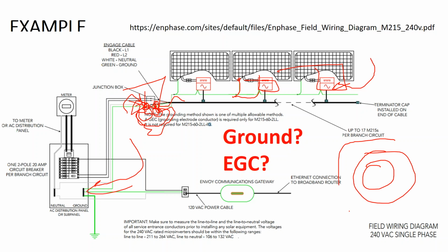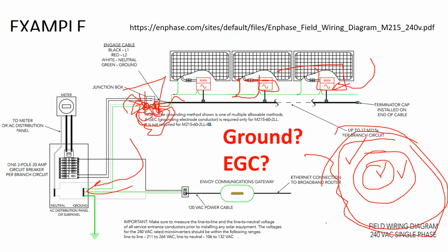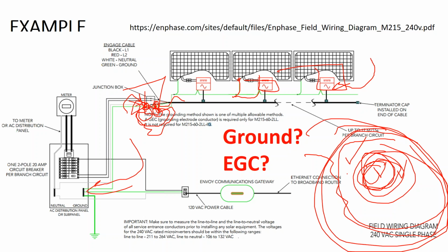Now, you also have an issue where when you get into these metal boxes, you have little knockout holes. And sometimes you have concentric knockout holes that have little dimples built into them so that you could put in 1/2-inch conduit, 3/4-inch conduit, or 1-inch conduit. And I only learned recently that if you use these concentric knockout holes and you put your metal conduit into the smallest hole rather than the largest hole, because this metal frame is dimpled for these concentric knockouts, that violates the ground path. And so if you're using a concentric knockout ring, you might have to have a fitting that connects to the ground bar. Whereas if you just use the outer diameter, you might not need to ground that fitting because it's listed to be grounded already.